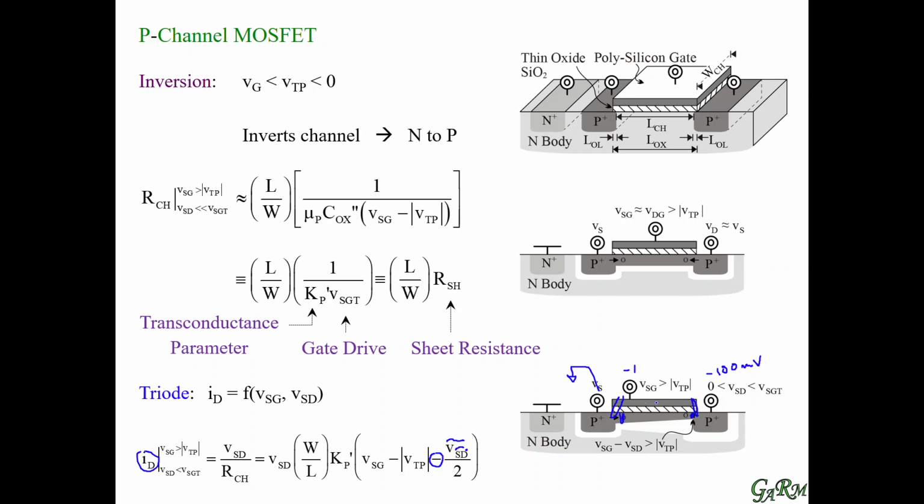One way to think of this is that we can divide the device in two. The right half side basically connects to the right terminal, the left hand side connects to the left hand terminal. And we're basically reducing the voltage across the gate oxide on the right half side. So this voltage here affects half the channel, so its effect is half here. But that's just a way of remembering. This is ultimately a correcting term that adjusts the resistance when we apply a voltage to the terminal all the way on the right.